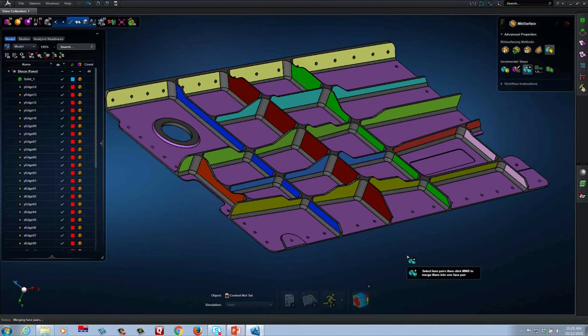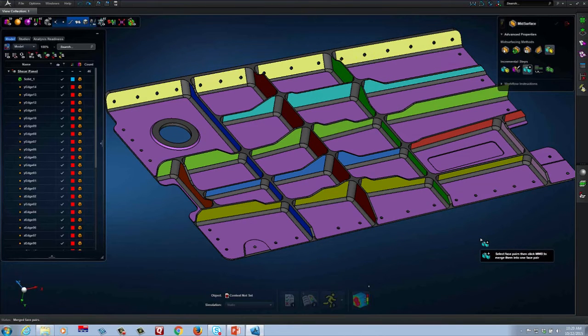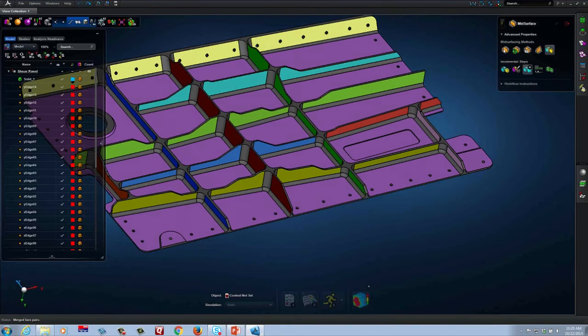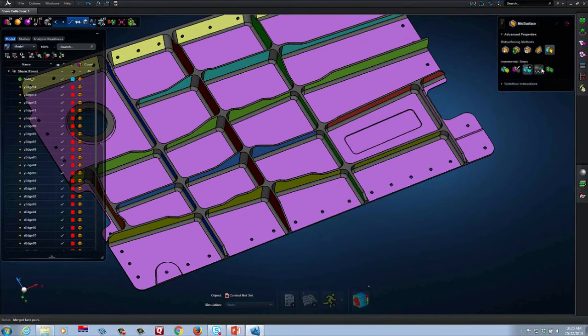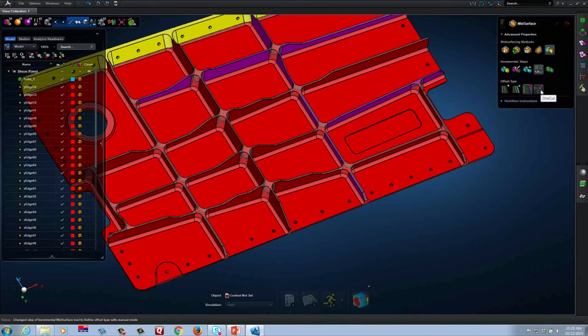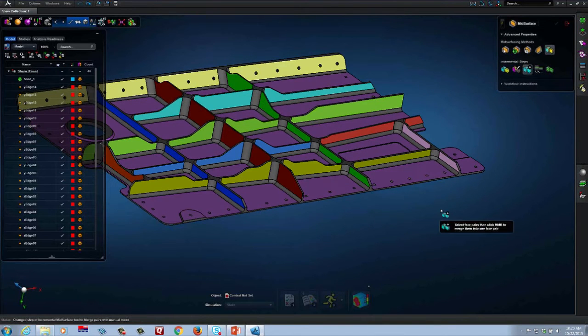I will have to say that merging the face pairs does not necessarily guarantee alignment, okay? I could actually have some offsets that were so large that it would potentially not be able to do that. In this case, it's absolutely going to work. For more difficult cases, we actually have a mid-surface extraction method we call one cut, which is a little bit even better, per se, for the more drastic situations. We don't have that here, so we'll just go with this.